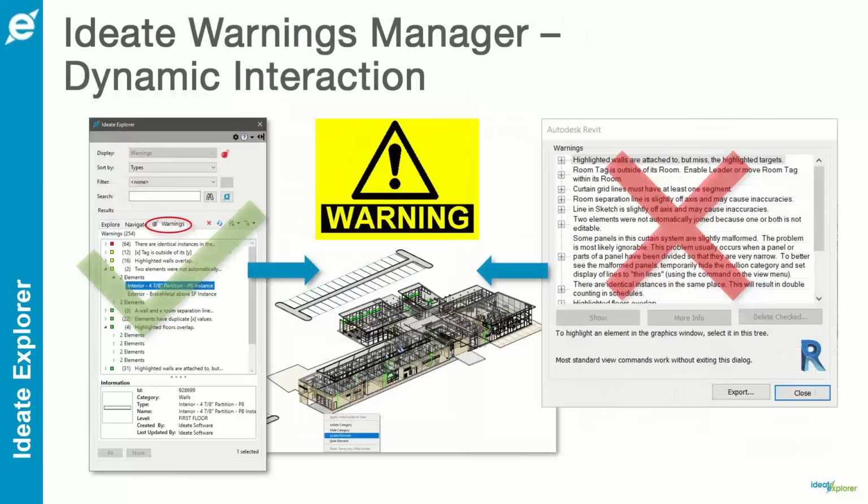And then in addition to the query, we also have warnings. This is critically important when you audit your Revit project. Warnings can potentially corrupt the model. They can certainly impact the performance. So it's very important that you review and fix warnings on a daily basis.